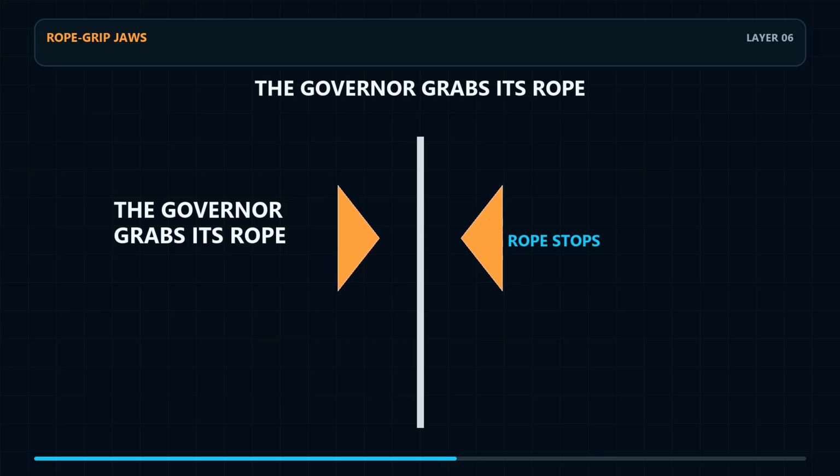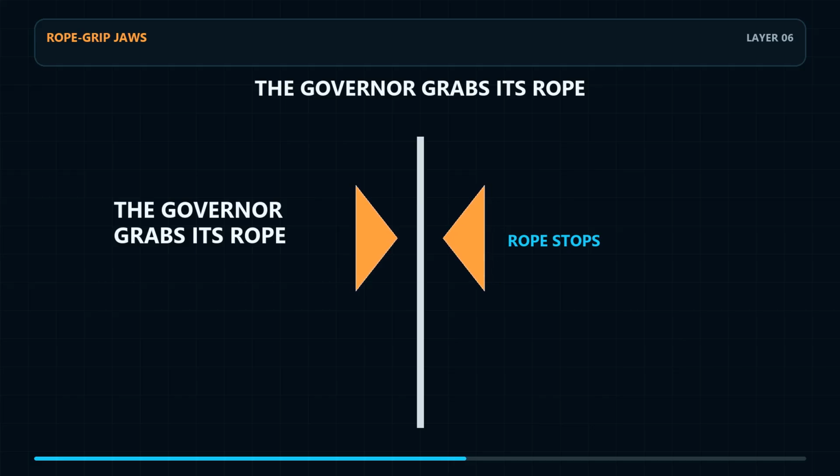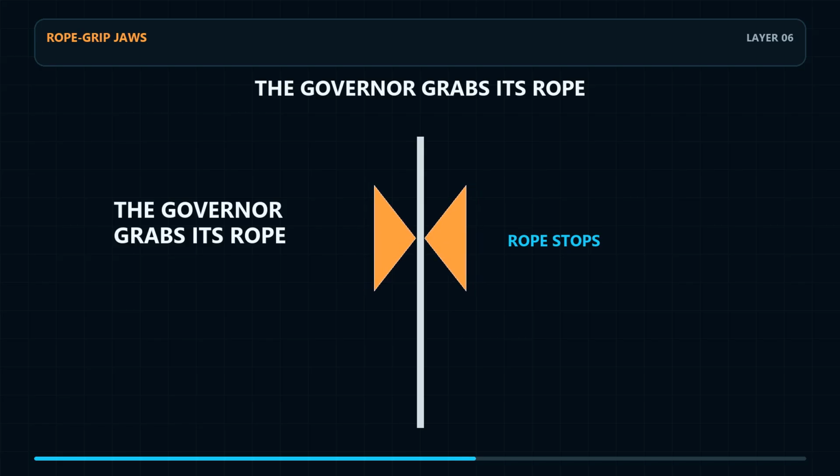This distinction matters. The governor does not reach down and clamp the passenger car. Its jaws seize the governor rope. Now the rope is stationary while the car and its frame still have downward motion. That difference in motion supplies the pull for the next mechanism. Stopping the rope is useful precisely because the car-mounted linkage remains in motion beside it.